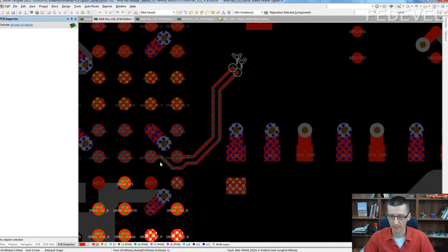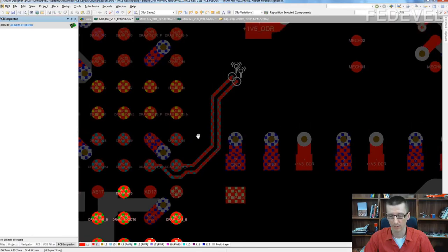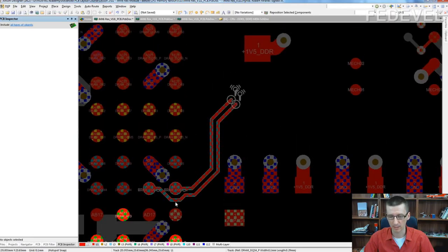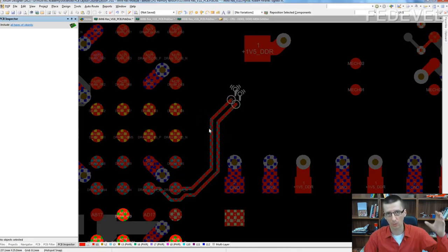I didn't place the through hole vias or the fan out close here to these two pairs. And I have a reason for it, because for these DQS signals, I prefer to take them out if possible. It gives me flexibility that I can choose where exactly I will go into the board, where exactly I will place the through hole vias.